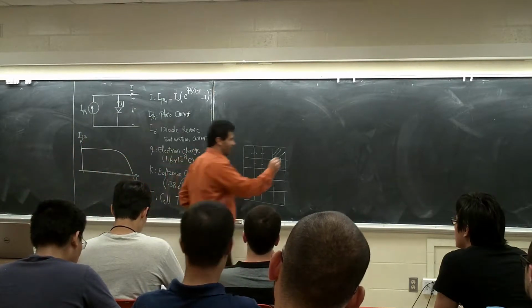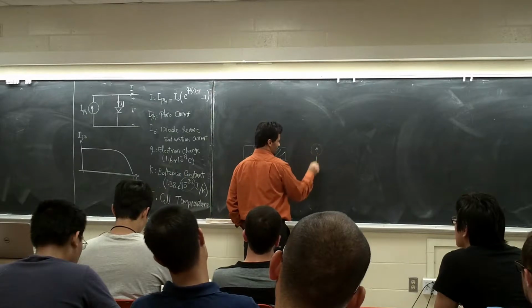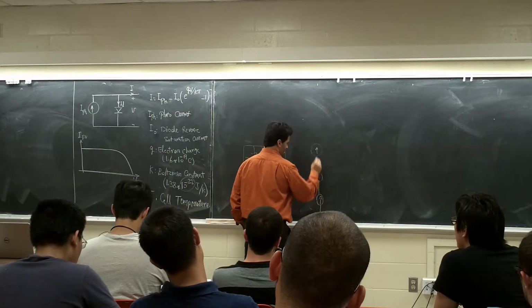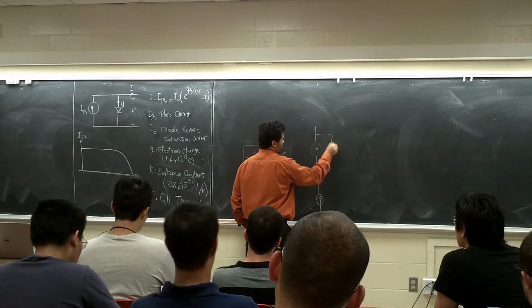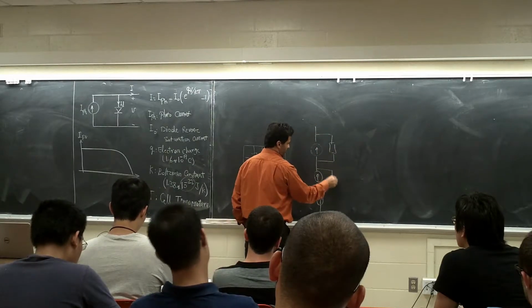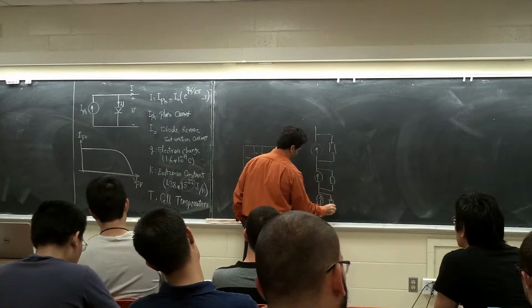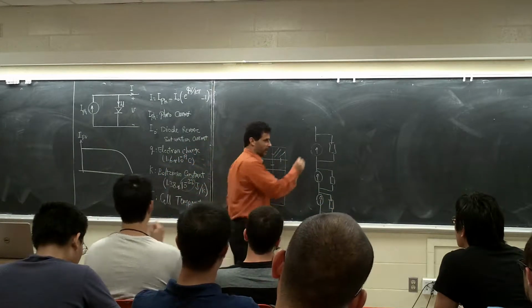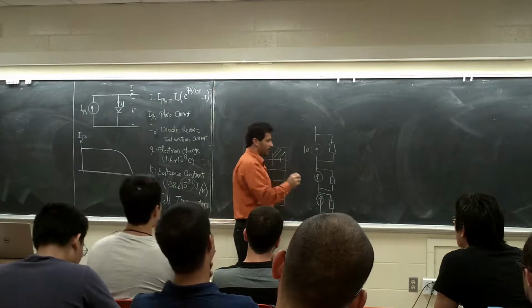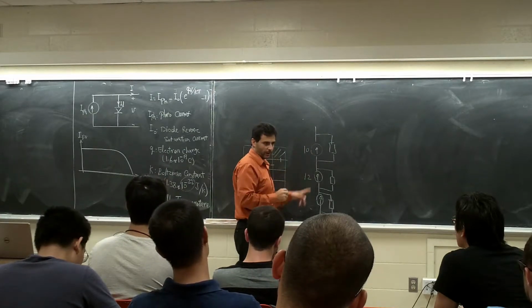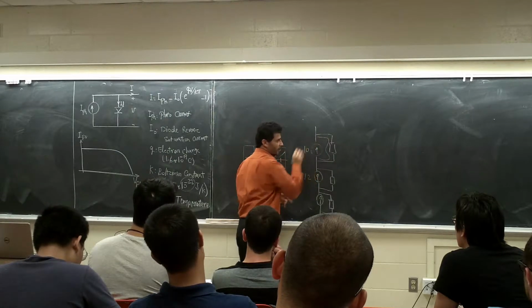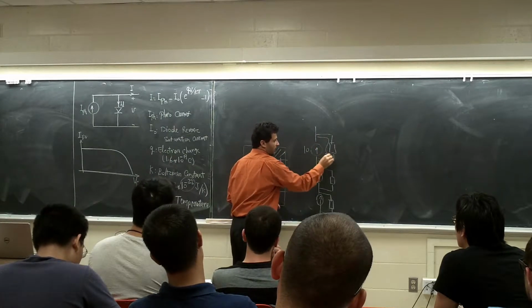If you look at this solar cell, they're like this, right? Now they put a box here, a small DC to DC converter. And this is expensive, that's the problem. What they do is, this one can go 10 amps, for example, that's fine. This one can go 12 amps, that's fine, right? There's a mismatch here, right? What is going to happen? The mismatch is going to go through here. 2 amps is going to go through here, right?